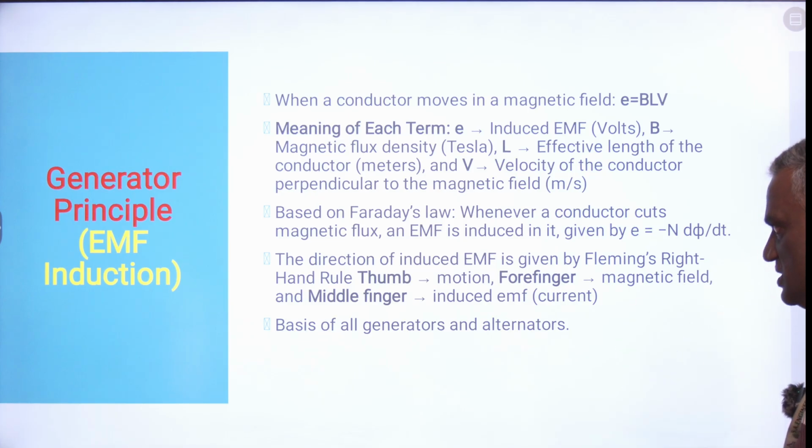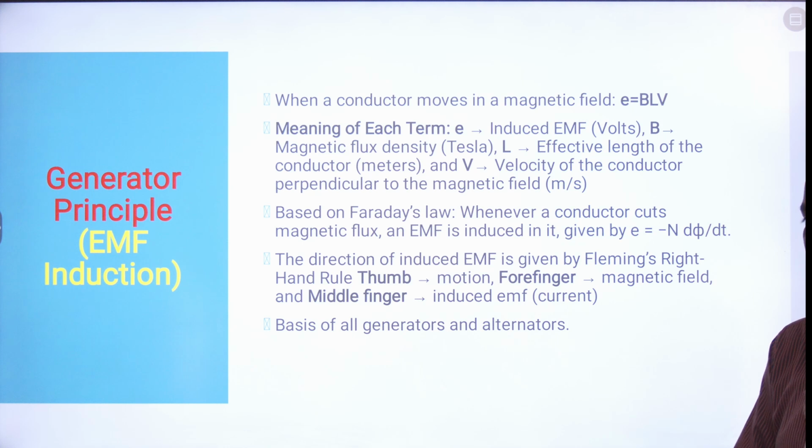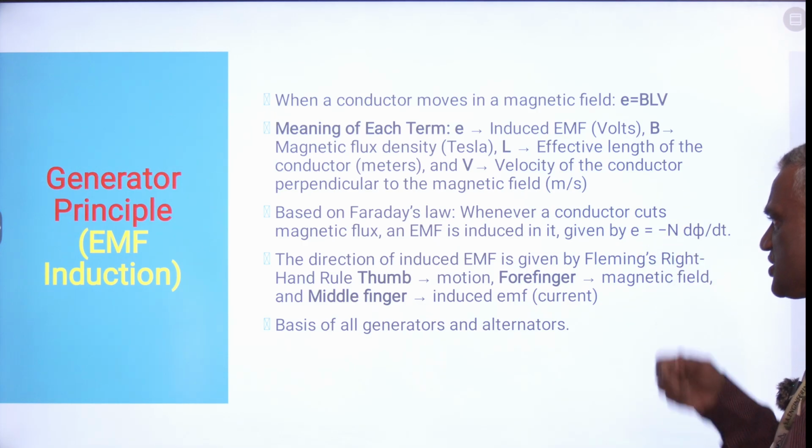So yes, that is Faraday's law. What Faraday's law says is whenever a conductor cuts a magnetic flux, an EMF will be induced in it, right? So as per this principle, E is minus N into d phi by dt. So this is induction of EMF.